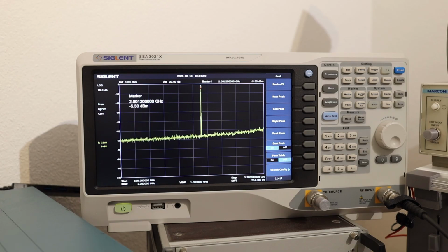At 2 gigahertz we see the output is very decent, clean, because the harmonics are not visible there. At this level of frequency, higher frequencies, the output is better in terms of harmonics than on lower frequencies. Amplitude is a little bit dropped, to around minus 5 dBm, but at this level it is quite expected. If you want, you could go to 4.4 gigahertz. Of course, it's not visible, so let's go to 3.1 gigahertz.